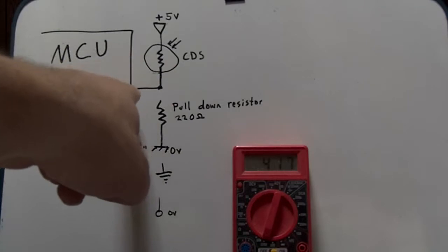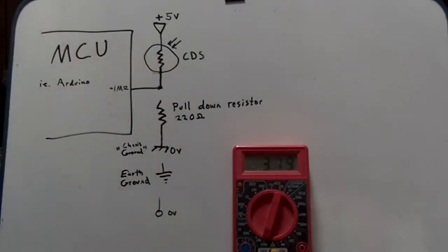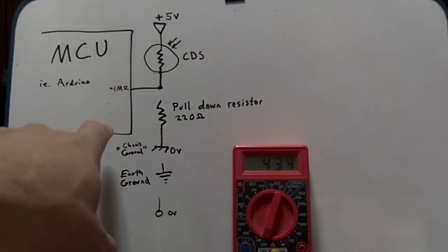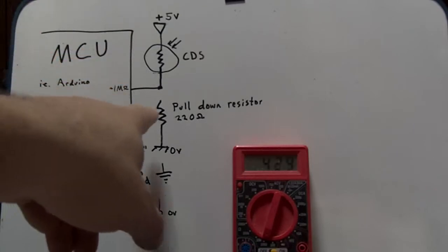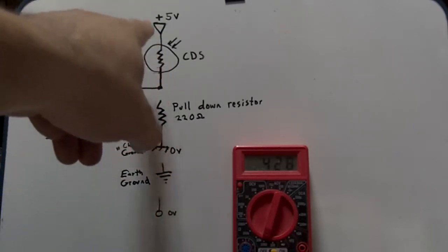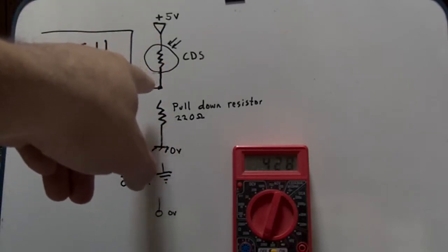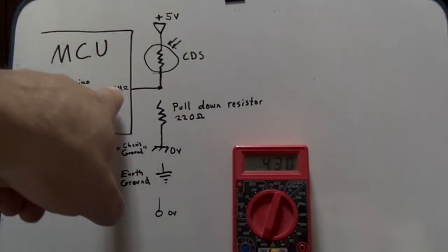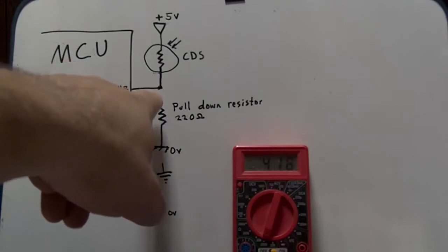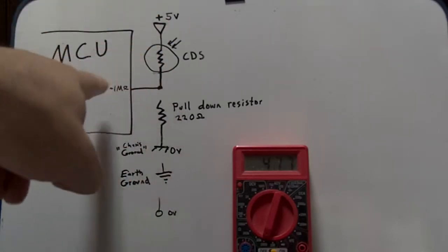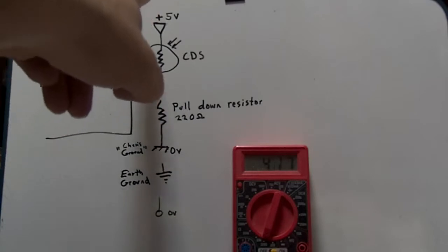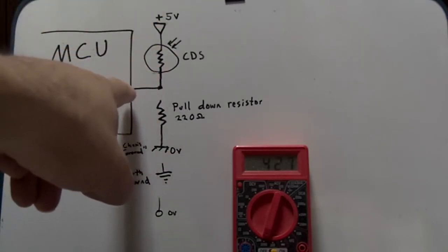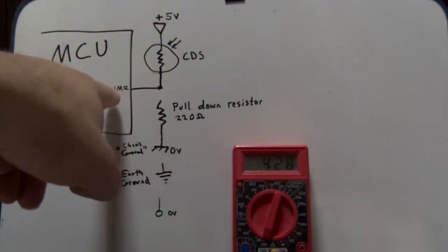1,500 dark down to 50 ohms bright. I'm pulling those out of the air. It's kind of close to what it is, but I'm pulling those out of the air. Let's say that's what it is, though. Well, even at 1,500 ohms in the dark, contrasted against that 1 meg, that's nothing. It's barely going to influence that 5 volts at all. All that 5 volts is going to pretty much be seen here, because this isn't enough resistance to compare against this 1 meg.